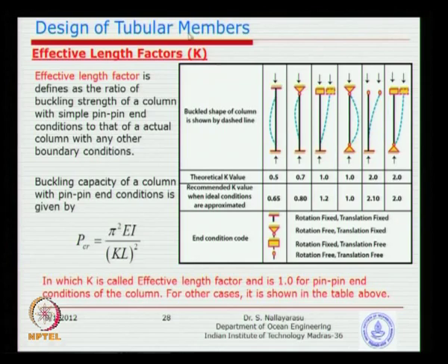So, basically this is quite important for any civil engineering construction, but fortunately most of the jacket structures we have are welded construction, number one, that means any beam or column is welded to another beam or column. Mostly you will get fixity close to partial fixity, that means you will get somewhere here, and that is the condition that we normally assume in the design, because over a period of time it has been established that tubular to tubular construction will go close to fixed condition.